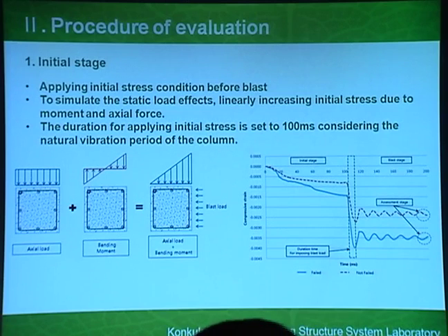If you see the graph, this is a typical structural behavior under blast. You can see the natural period of the column is about 15 milliseconds, so if you apply the initial stress over 100 milliseconds, it is much closer to a static load.